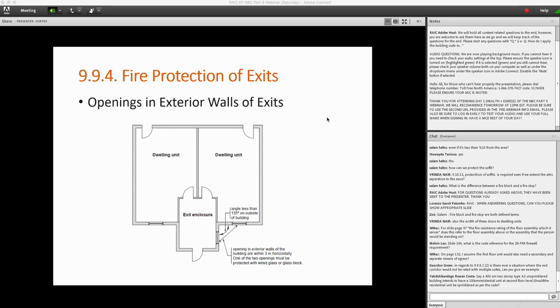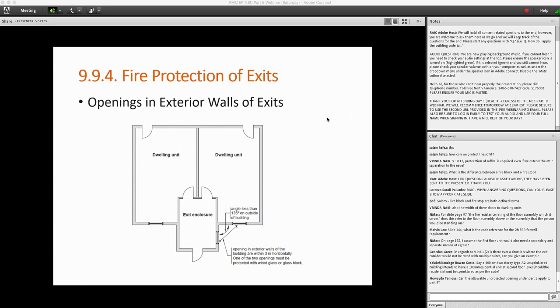Question 8, how far does the second door need to be provided? Yeah, so I believe this is related to when you are required to have 2 egress doors from a room or a suite. So Part 9 of the code is very silent on this. It just says that they have to be remote from each other. But you can apply the same principle that is used in Part 3 of the code, where you measure the maximum diagonal dimension of the room or suite, and then locate these 2 doors remote from each other by a distance of not less than 1/3 of this maximum diagonal dimension.